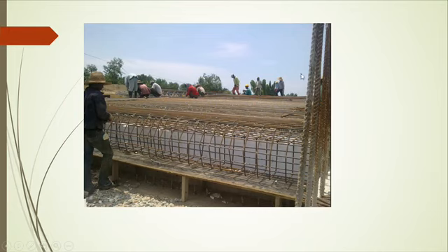So this is steel, as you can see here, a projection, or we call it a rib. We have a projection on the steel to increase the friction between the reinforcing steel and concrete. This bar is for the wing wall of the bridge. So the wing wall, and then to the parapet of the bridge. So basically it serves as the guard